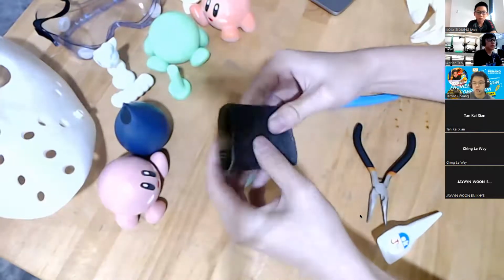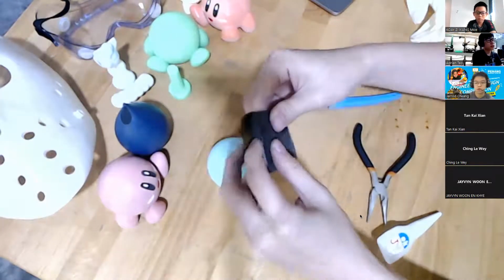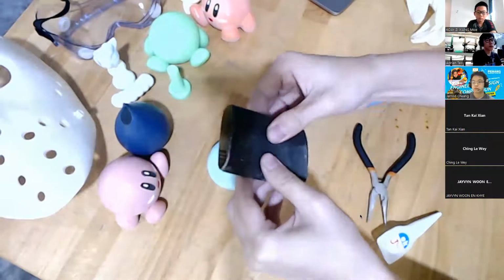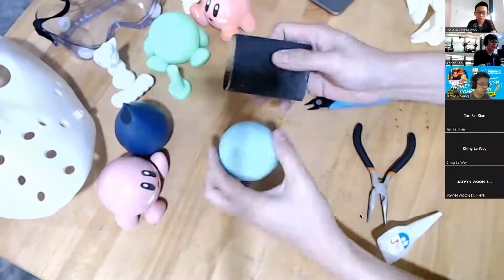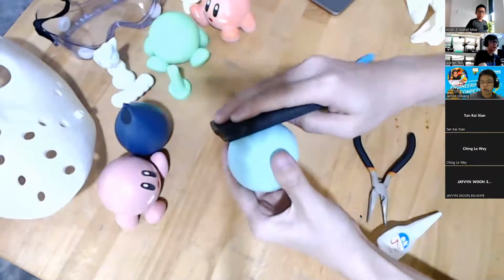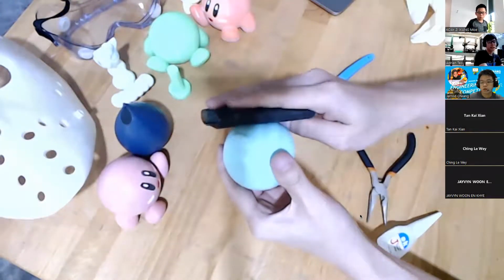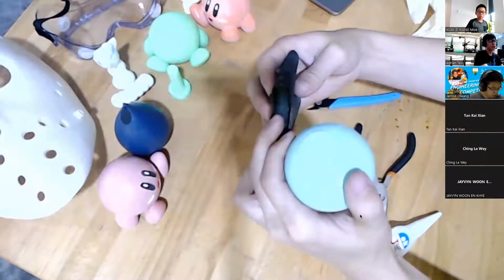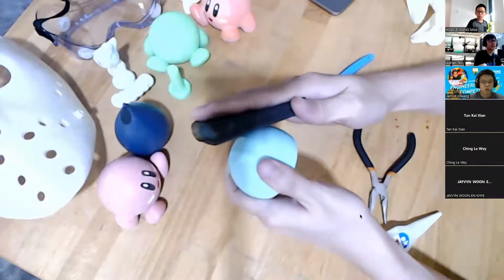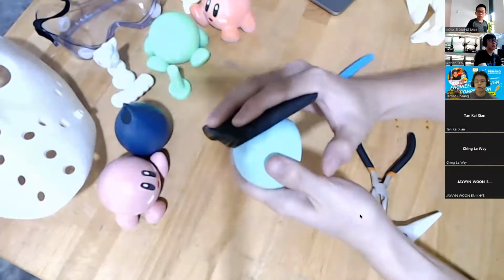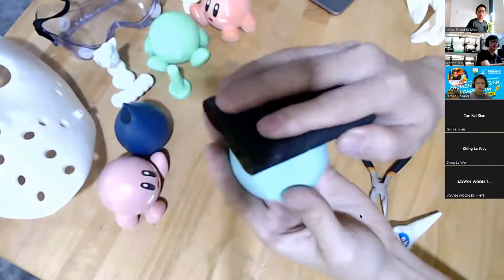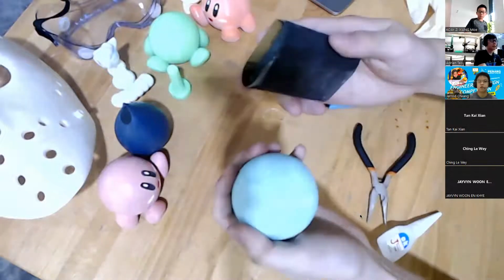Normally for woodworking, we put something harder, but for 3D printed parts, I prefer something soft inside, so that you can actually curve your sandpaper together with the print and then sand. If you put a wooden piece inside here, it will be hard. So you are only sanding this area, but with a sponge, you can actually press it down and then sand a more curvy area.